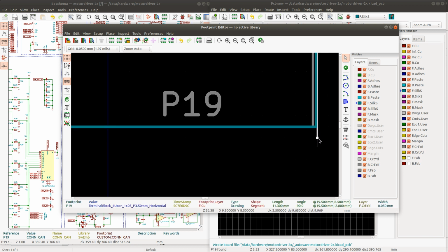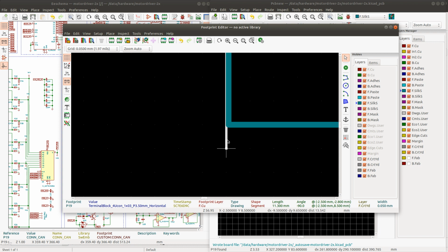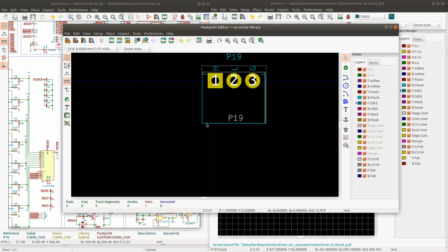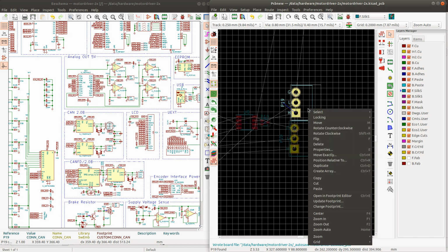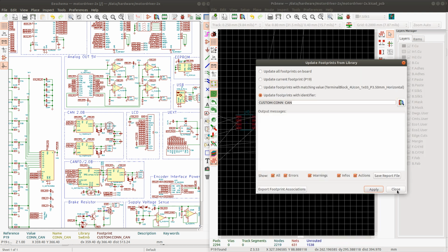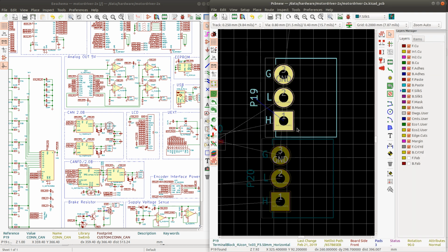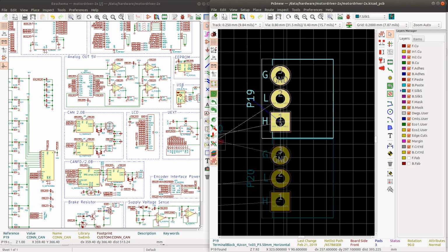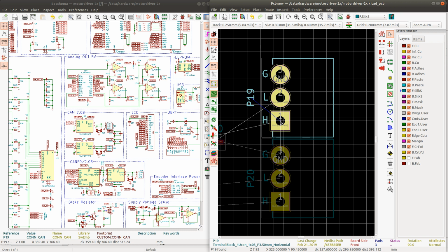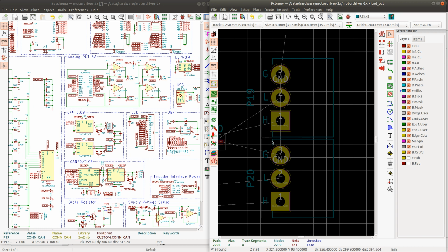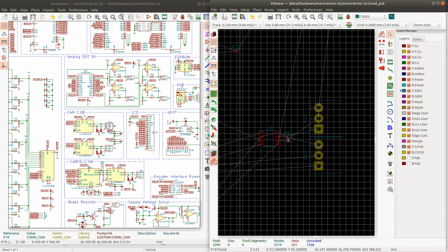And the courtyard on the PCB edge side is going to be aligned with the silk screen. All right, let's save this and update this. That's better. So now we can place them not fully, totally close, so I leave a little bit between the components, but at least I know that the component is not going to be protruding any more than this silk screen. So that's good.